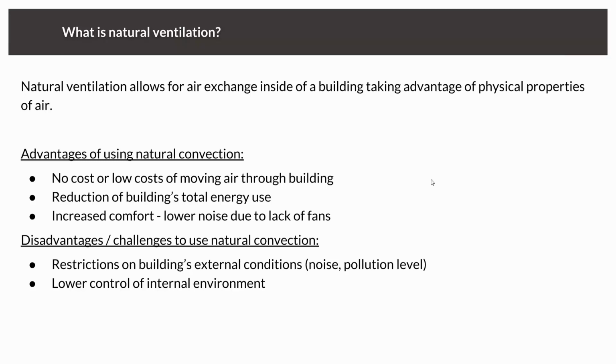First of all, it's not possible everywhere because you need enough average wind, and you also need to make sure that the openings allow it, because you cannot build in any filters, or it's hard to build them in. The other external conditions of your project must also allow it, like that you don't have any noise outside, and if the building is in the middle of the desert, it's questionable if it's really smart to do natural ventilation.